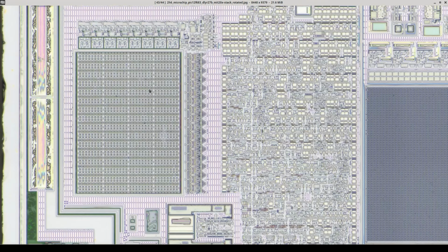And so perhaps what we're seeing here is this 8 bits is the low bits that are used when you're storing constants in program memory for indirect access over the data bus. And then this is the full 14-bit bus used for instruction fetches. We're going to take a more detailed look at the flash later on. For now, let's move to the left.